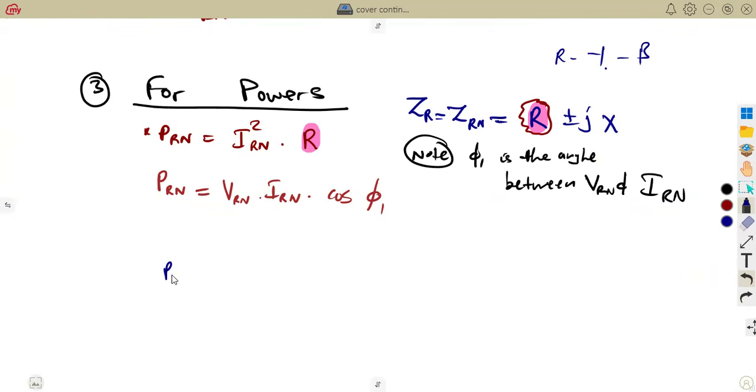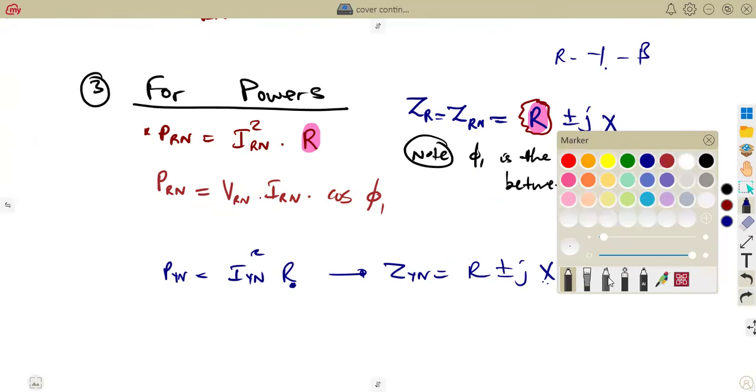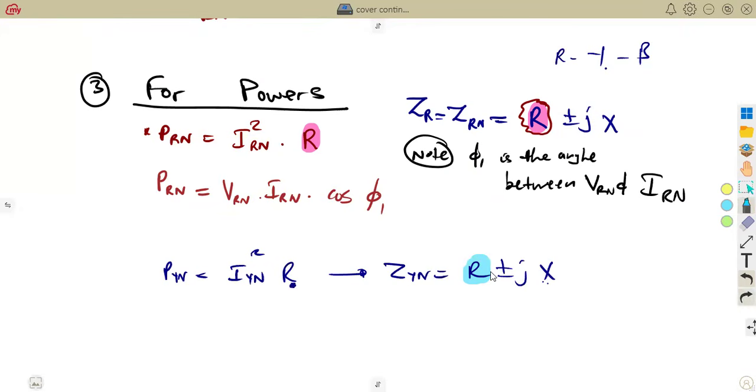It's just going to be a repetition for the yellow phase. So it will be the current for the yellow phase. The resistance that you need here is from the yellow phase, from the Z of the yellow phase. That is where you take it. Remember, you'll be given R, whatever that you have, plus or minus JX. The resistance here is the one that you need in that calculation. This one, you already calculated it.